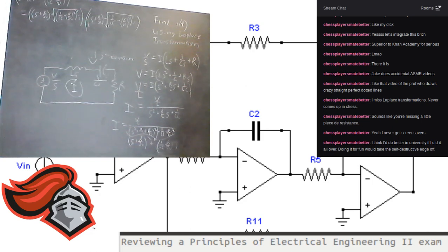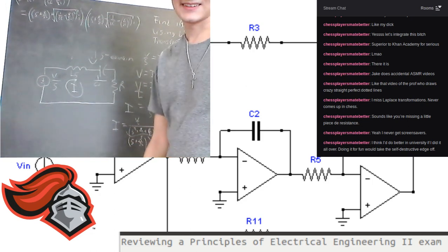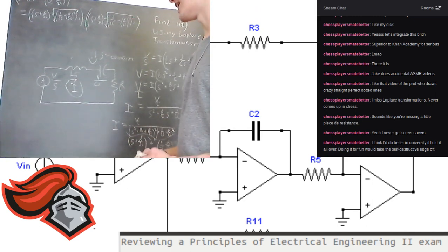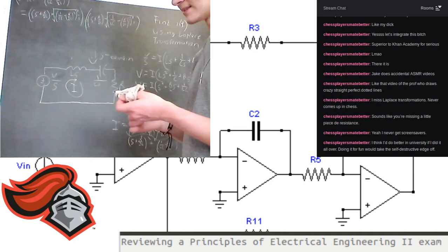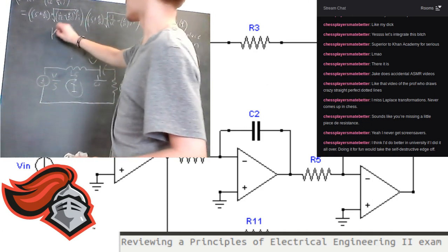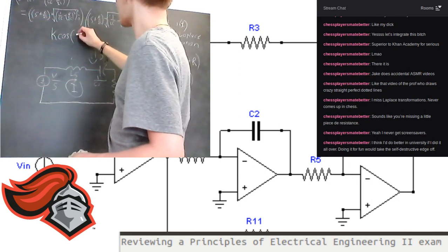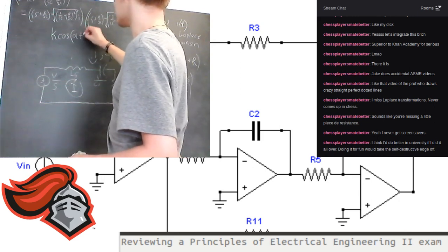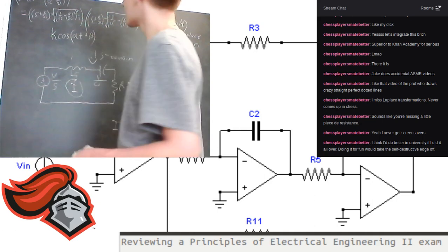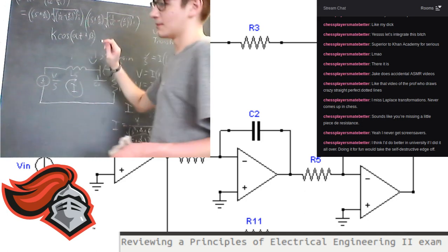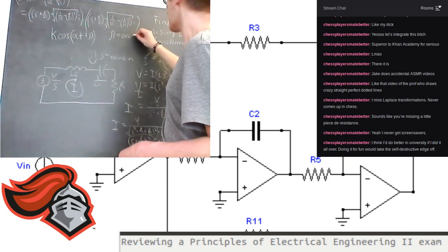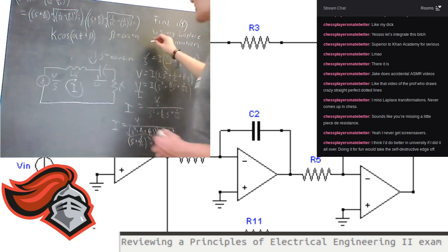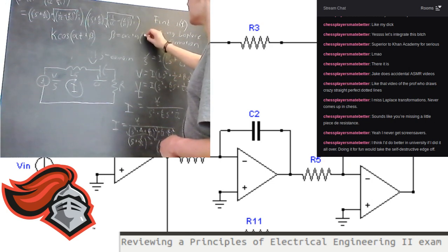Neat. So now that that's fully factored, you do the partial fraction expansion, and then you can convert it back into the time domain, and you end up with some constant times cosine of alpha t plus beta, where beta is given by, if you do the partial fraction expansion, you get a complex number in the numerator. So it's b over a.